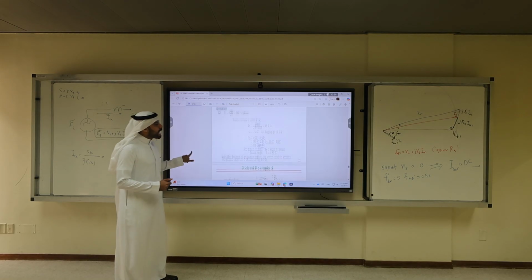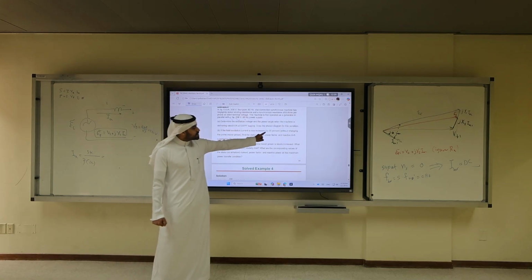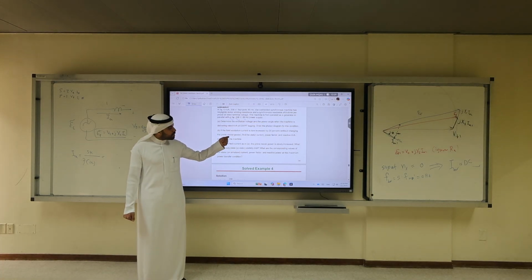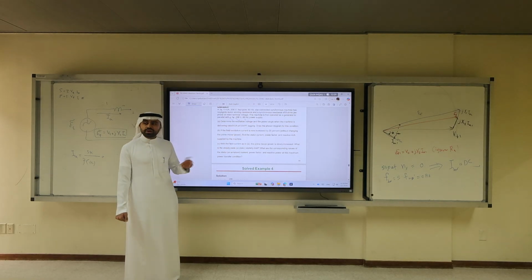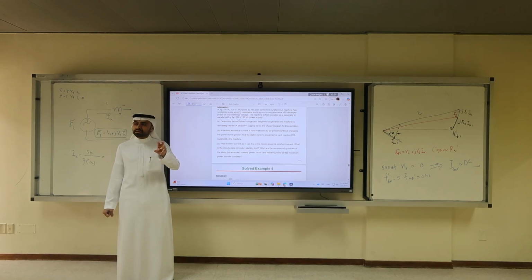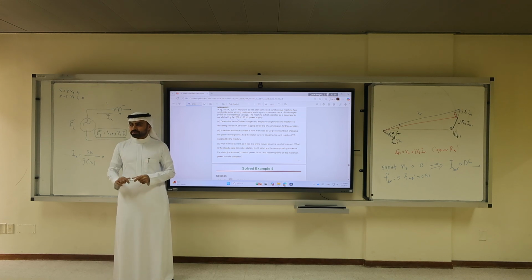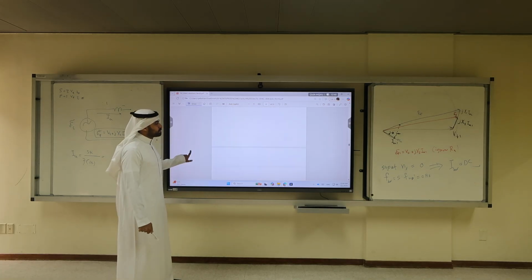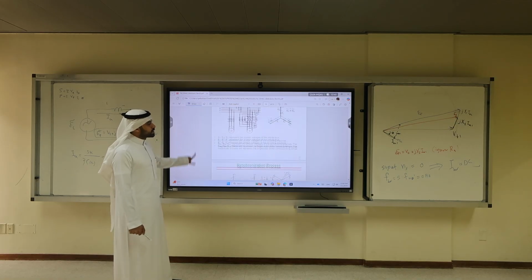Now, what is happening in part B? If the field excitation current is increased by 20% without changing the input power, find the stator current, power factor, and reactive power supplied by the machine. So here is one piece of information: if I increase the field current by 20%, what will happen to the excitation voltage? Drop? No. Increase? No. Go back to this curve, one of the early curves that I put here.